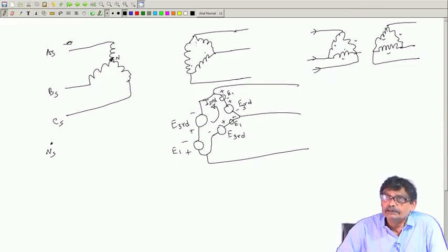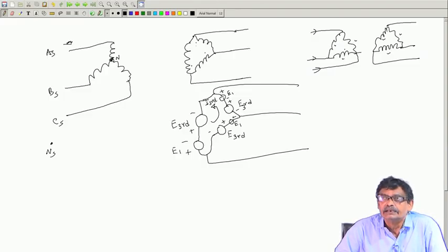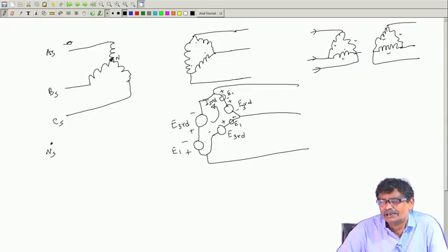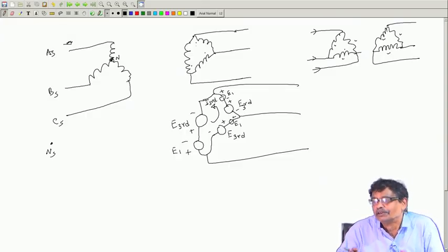Therefore, having a delta winding on a transformer connection becomes perhaps a very good option. With one winding delta in the transformer connection, at least you can get relief from these third harmonic problems, you do not have to think too much.